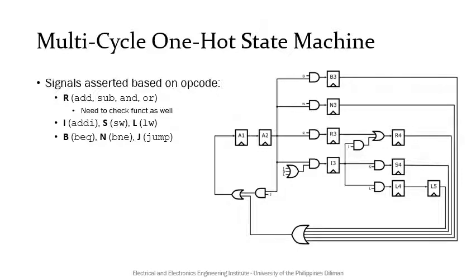must be included within the control unit. From the state transition diagram, we can construct this hardware if we look at when each state becomes active. For example, we go to A2, or give A2 a value of 1, only if we are from A1. Thus, we simply need to connect the D input of A2 to the Q output of A1.